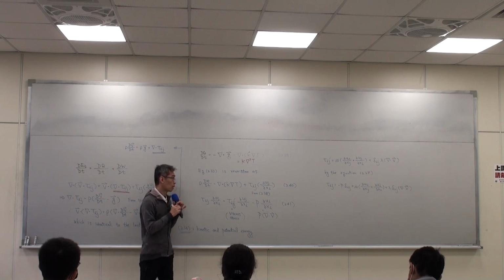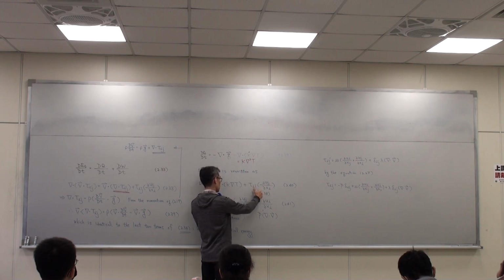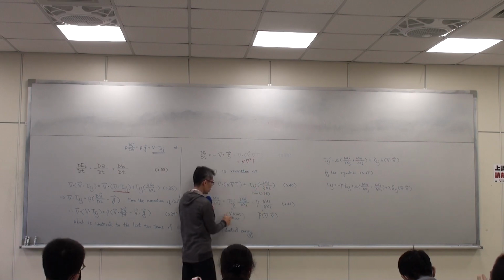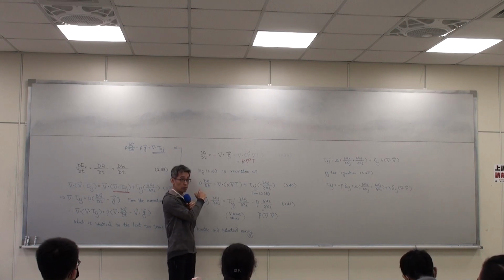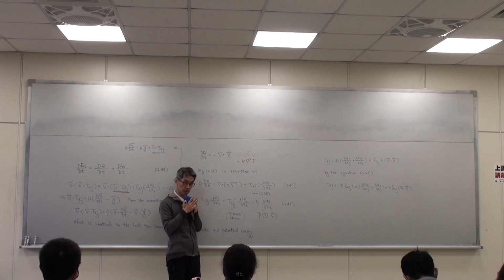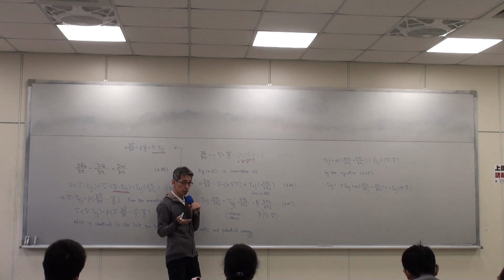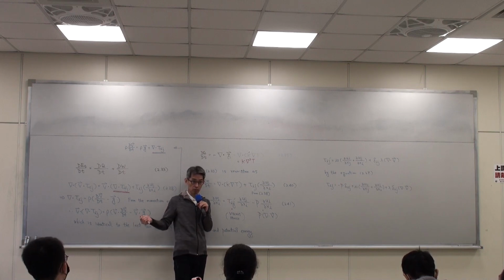Okay? So lastly, we can see there are some contributions from this kind of stress. Basically, it is viscous stress that will contribute to this kind of internal energy. That means your system will increase in temperature. This increased temperature, because of viscosity or friction, and this reduced energy make the Bernoulli equation lose its mechanical energy.